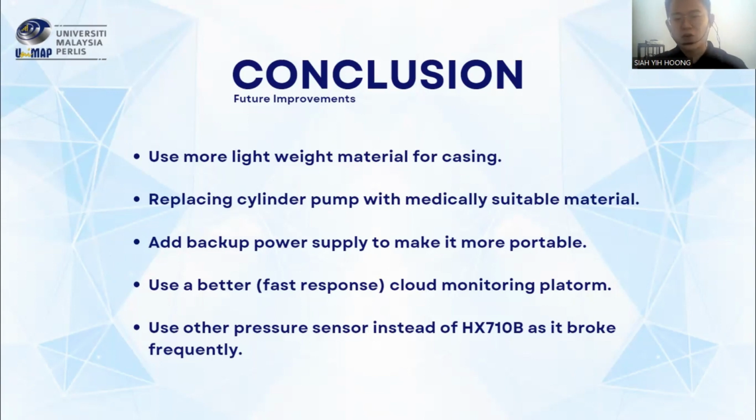And also for the HX710B pressure sensor, this pressure sensor is from China, and it really easily gets broken. So if we want to use it for the long term, it is better to use another pressure sensor that can work for a longer period of time. It will also be, I have to say, easier to program, because the HX710B lacks a datasheet, so it is really tough to find suitable libraries to code it.